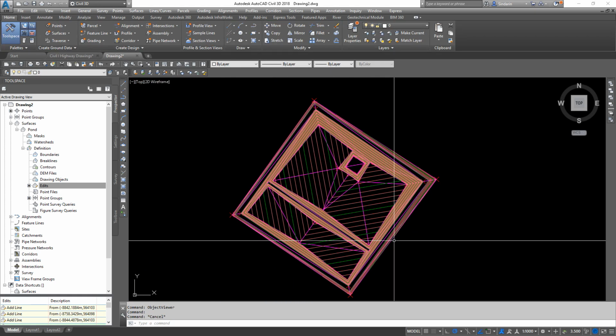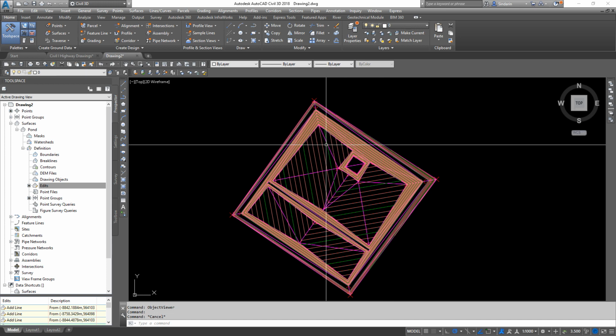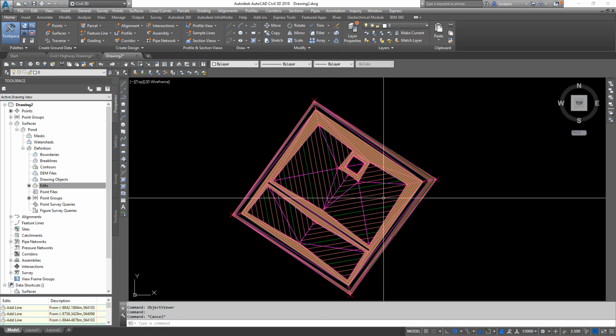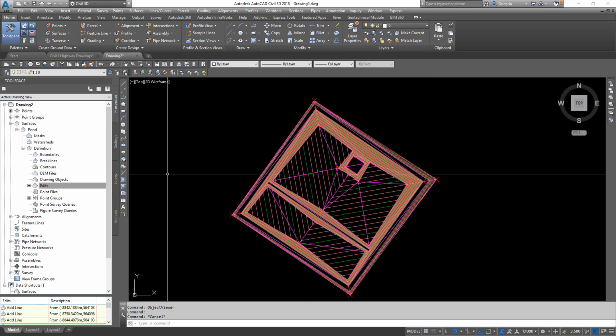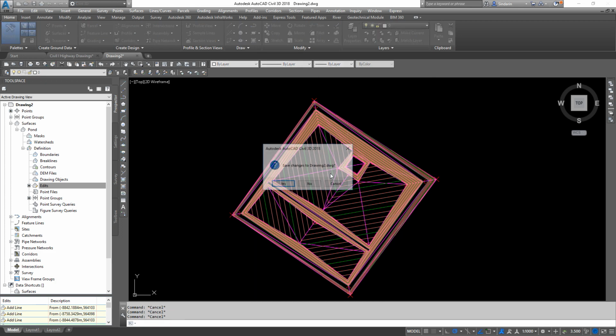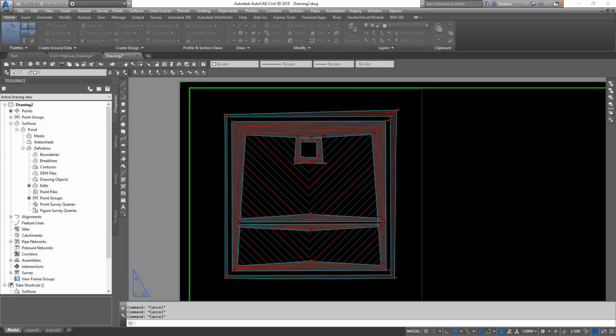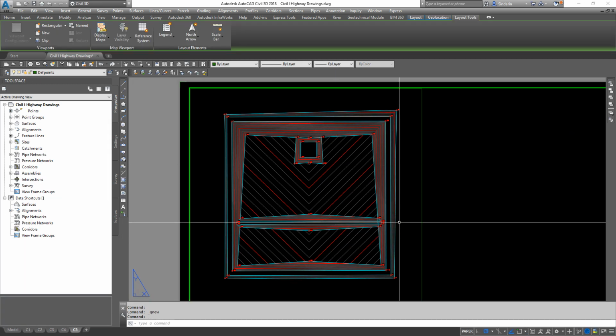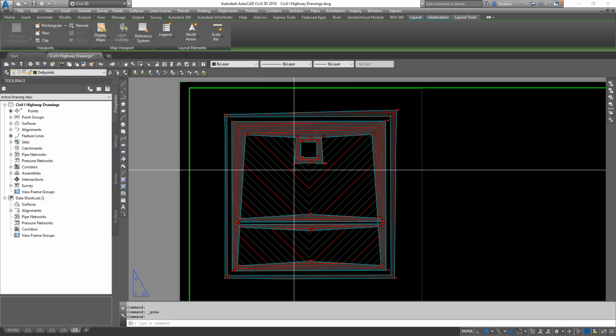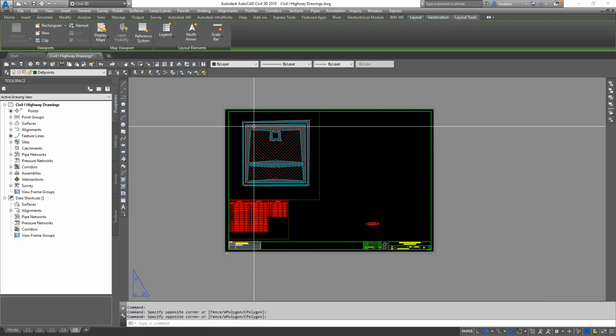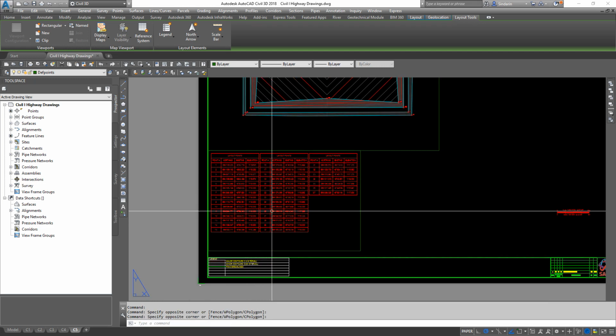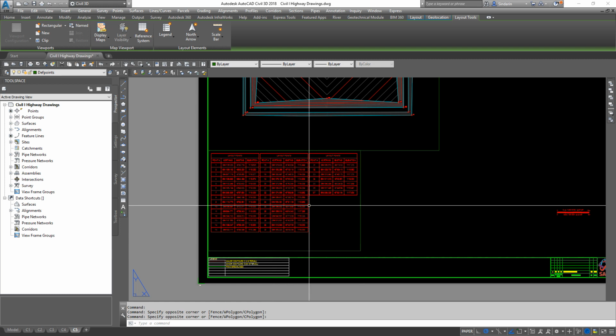Now we've only gone and done the outside, the important corners. Again, this is big enough that there would be a grid of points possibly inside the pond as well. A grid of points midway up the berms. That's a lot more work, but generally we will need more survey information to build this. But for now, this is all that we're looking for. It just defines the hard edges, the hard break lines.